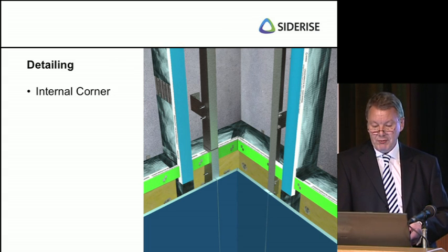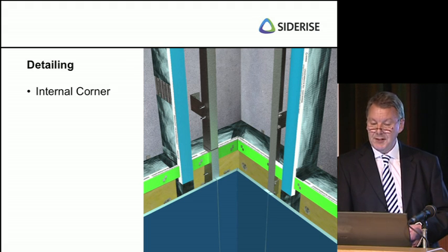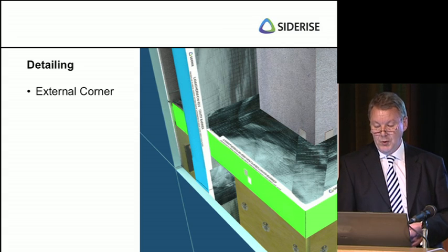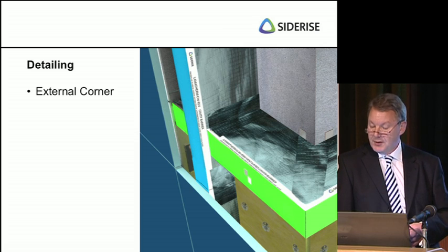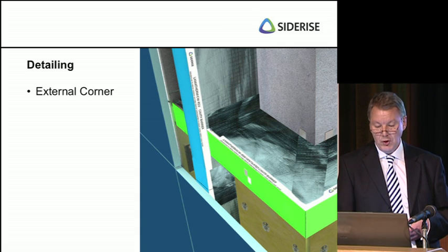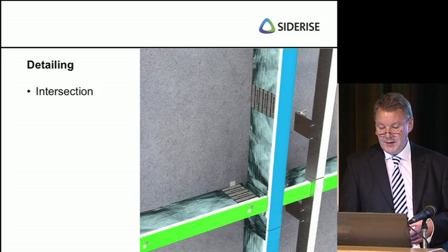It's a clearer illustration where you can see that the horizontal barrier is effectively set back from the full width vertical barrier. It's a similar treatment at the external corner condition. Vertical barriers are installed first at full cavity, horizontal barriers installed within them and the joint between them tightly abutted, joints foil taped. Here's the intersection.